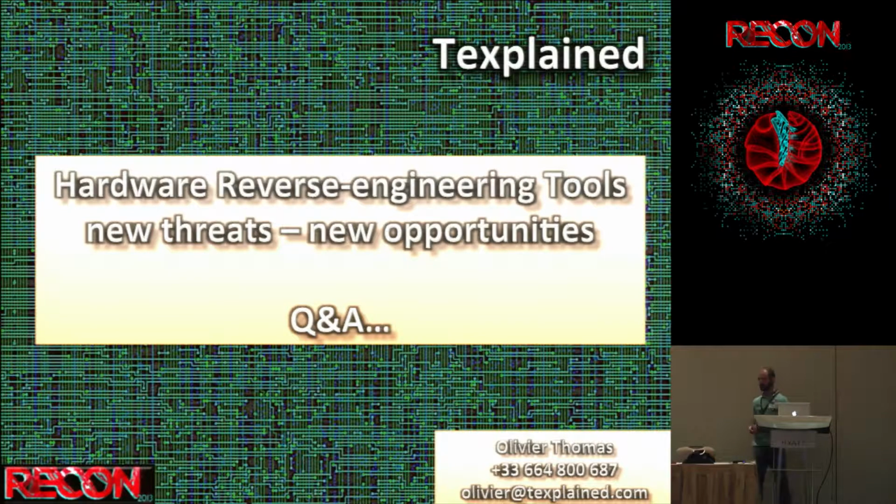So the first one is, can we use this technique on something much bigger than just a little smart card? Yes. I was trying it on a chipset that was a piece of a die, like a 1 centimeter square die, with I don't know how many transistors, but really a lot. It was 90 nanometer technology on 8 layers, I guess, and it's the same. Basically, the size doesn't count. You just have more data, but it doesn't change anything.